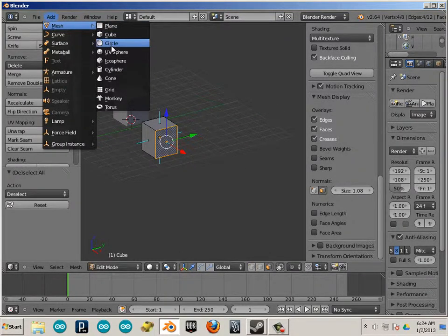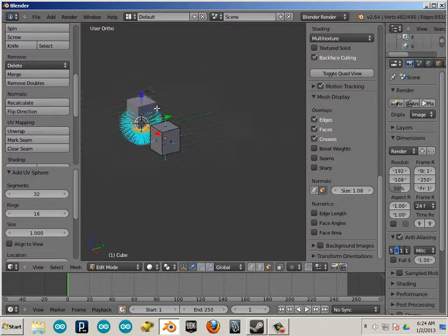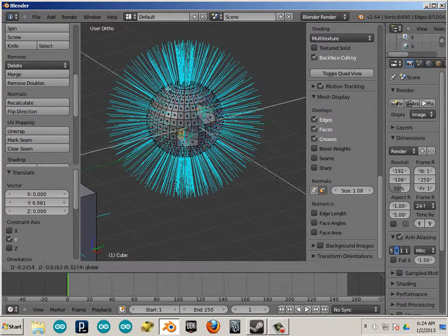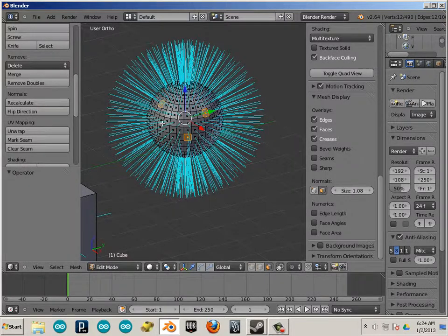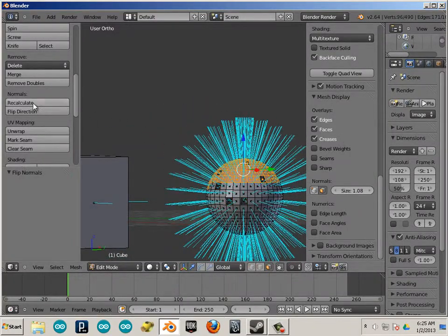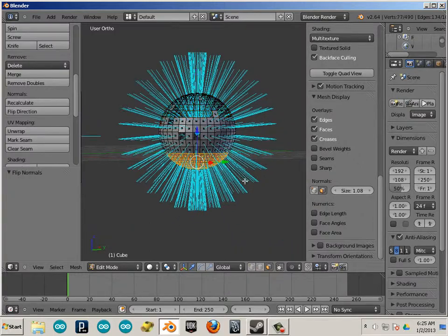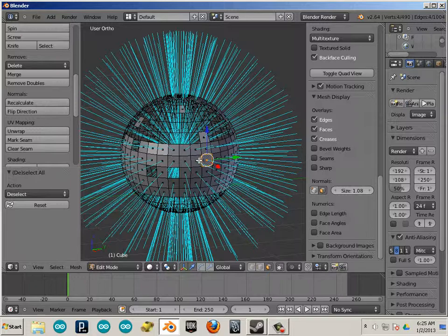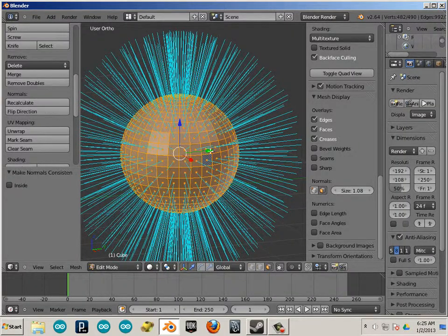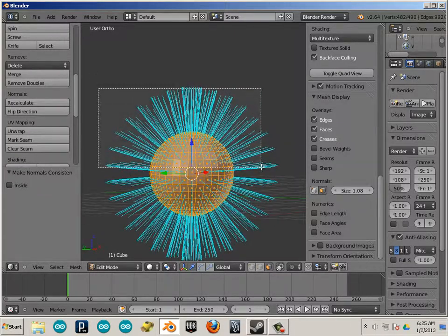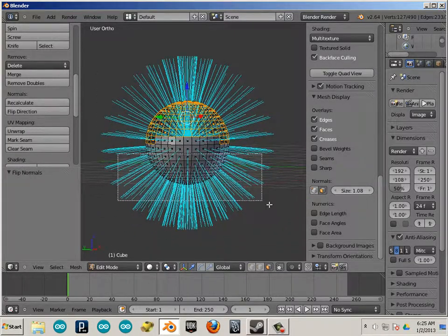Let's say I had something a little bit more complex like a UV sphere. And I went randomly in and said, well, these faces right here, they're going to be flipped. And let's say the whole entire top shell is flipped. And these are flipped. At some point it fails. So I can hit recalculate. It worked out well. But if it was past 50% of the actual outside surface, it will not recalculate.